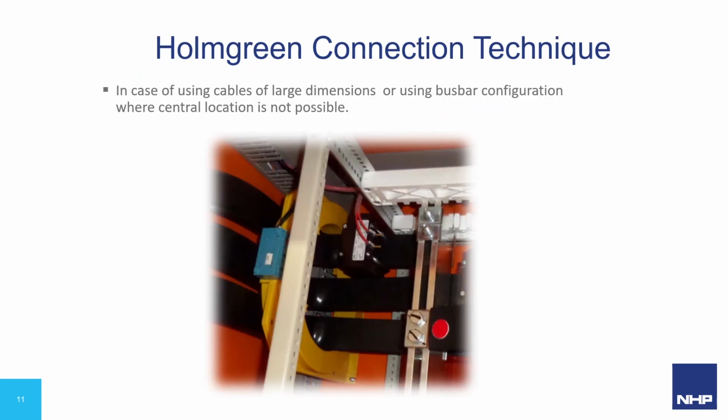Let's now look at some other unusual situations and applications and work with some issues we've discovered along our journey in the application engineering field over time. There may be some situations where cables are too large to fit through the toroid or where the use of bus bars in the switchboard makes it impossible to successfully mount the appropriate toroid. In the case shown here, tripping was caused by the failure of the middle bar to induce a balanced amount of current into the toroid.